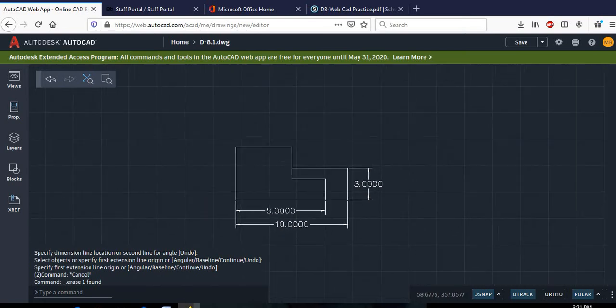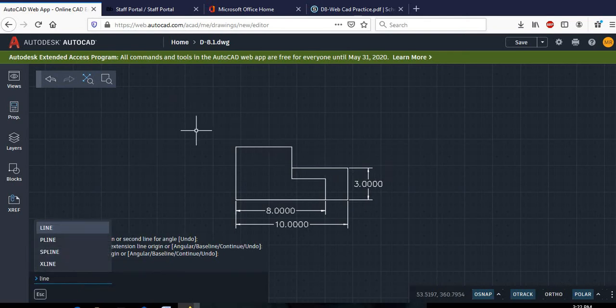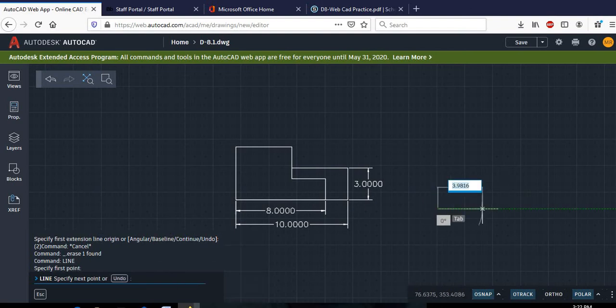The other thing I wanted to show you before I save is to get the ISO view. So right now, if I'm in the line tool, this is snapping to 0, 90, 180. By snapping, it's making those neon green lines.